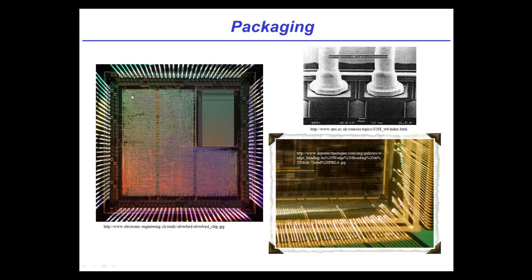But inside, going from the die to the internals of the package are these little tiny wires, and this is called wire bonding. There are machines that will bond one end of a tiny wire, tens of microns in diameter, down to one of the little pieces of metal on the silicon. They're called pads. They're the ends of interconnect. So here's an example of one. And they'll bring this wire down and apply a combination of pressure, heat, and ultrasonic energy to bond on a stubby end of it. And then it'll guide the remainder of the wire in a loop, sometimes a very tight loop. You see multiple pictures.